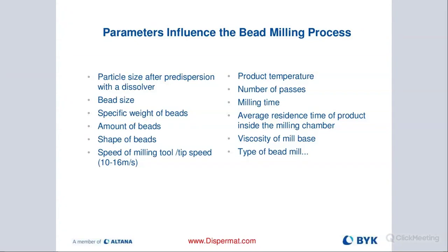Sometimes they're not even round anymore. They're more oval in shape. They're shards. So that's usually really a problem with the glass beads. You don't see that as much with the ceramic beads, but you should still keep an eye out and possibly screen them and get rid of the ones that are wearing down quicker.